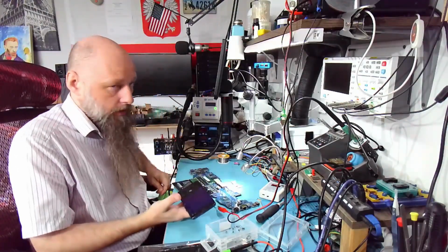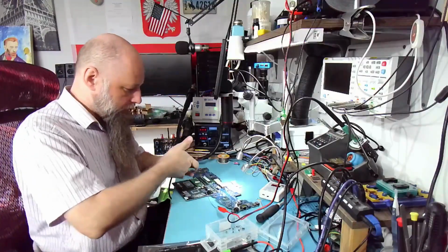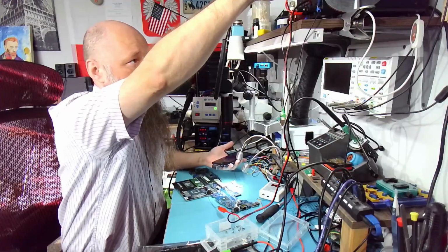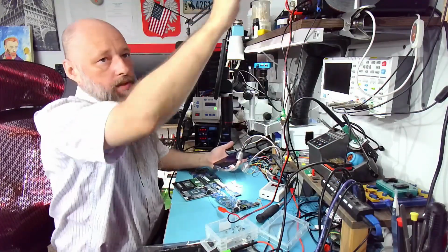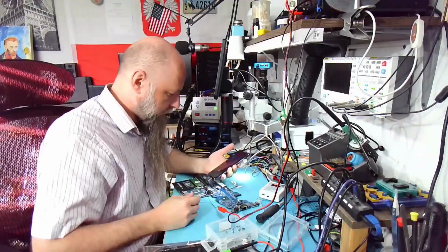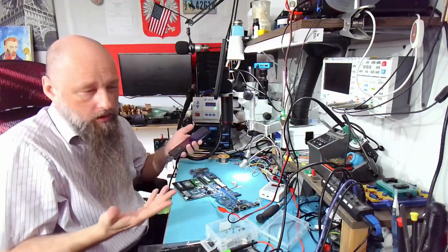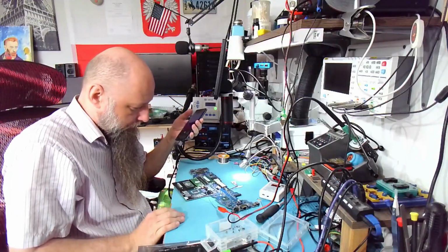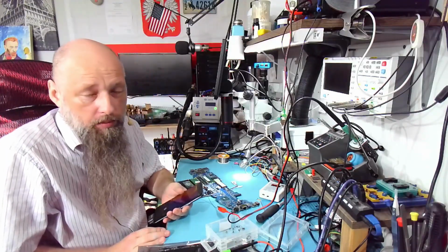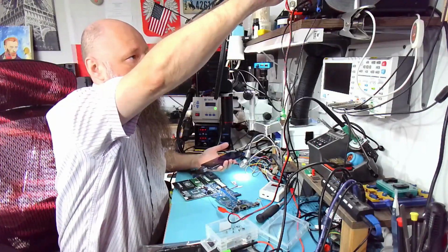Okay, I don't see any VRM lighting up, but that doesn't mean anything yet. Let's try increasing the current to 600. That still is relatively safe. And let's keep going. All right, this is 0.1 watt that we're pushing here, 100 milliwatts. That might not be enough for the VRM to light up. So let's just keep going.